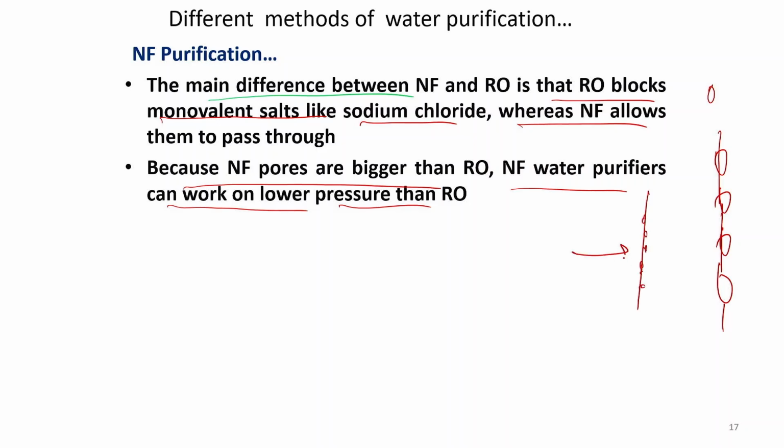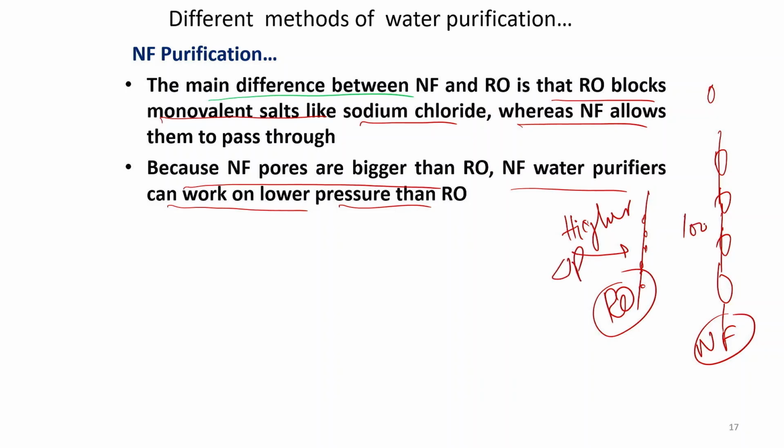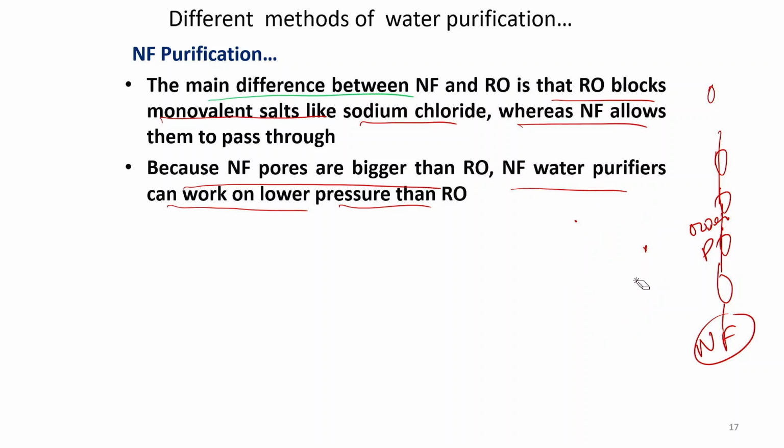So, here with RO we need higher pressure, and with the nanofilter we can use a lower pressure drop, because the pore sizes are larger than the RO.